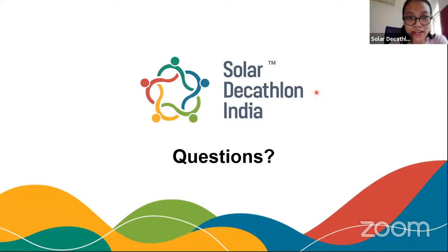So Shivani, another thing is that in your first submission, we asked for a shoebox analysis, right? So window to wall area ratio can be one of the analyses that you could include in your shoebox analysis, where you put in your weather data and then figure out which ratio works the best. It can be in terms of energy reduction, things like that. So you can do more analysis based on the wall to window area ratio.